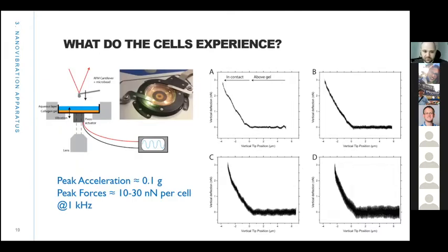We've checked this in reality using AFM, atomic force microscopy, where we vibrated collagen gels using piezo actuators in the presence of an AFM cantilever with a bead, making force measurements of the collagen gel. Initially, we were looking for signs of strain hardening within the collagen material as the vibration was applying quite high frequencies to the material.